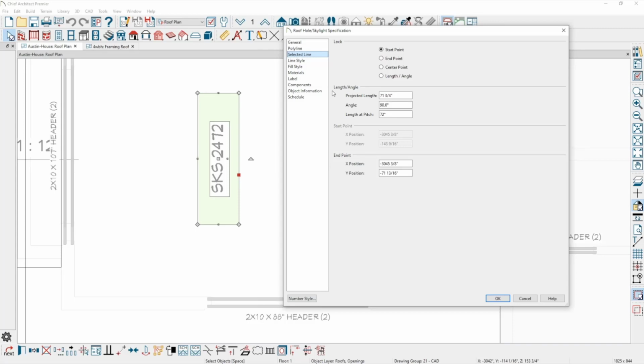Because there is the math part of it where there's a slope factor to the roof, and like a 12/12 is like 1.41 something or other. You could do the math to figure out what each thing should be. It's just more of like when you do it so it looks right in the 3D, it looks wrong in plan, and when you do it right in the plan, it looks really wrong in 3D. Yeah. I typically just stick with the model. And if it's a 6-foot skylight, it's a 6-foot skylight. Right here, you've got some numbers that you can set that CAD box from if you want to use that.